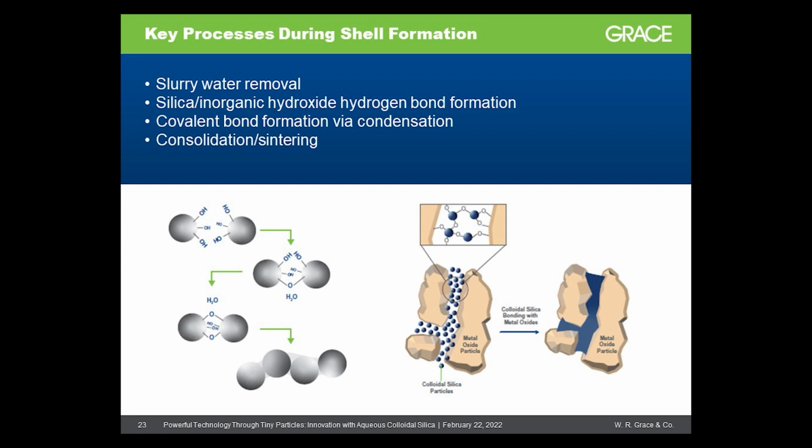as the particle size. After drying, the shell is then heated at elevated temperature, and this drives off chemically bonded water by condensation of surface hydroxyl groups. Finally, at even higher temperatures, the small colloidal silica particles sinter to form relatively dense regions between the refractory grains.